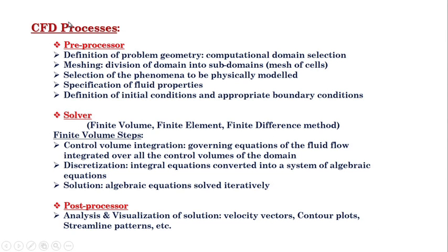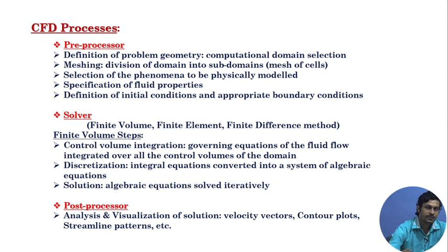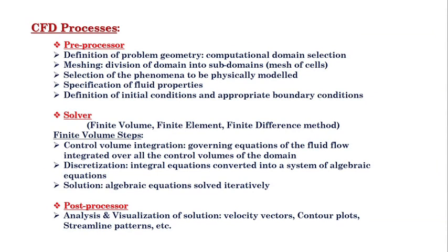Next question, how CFD? For CFD simulations, we have many commercially available software like ANSYS CFX, ANSYS Fluent, Comsol, Star-CD, and freely available software like Gerris and OpenFOAM, or you can develop your own in-house code. But one thing common to all the packages is that they contain three elements: preprocessor, solver, and postprocessor.